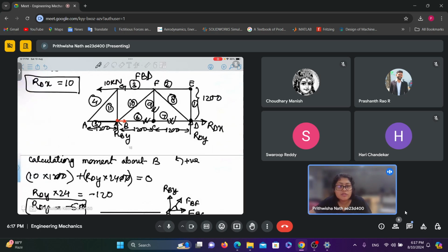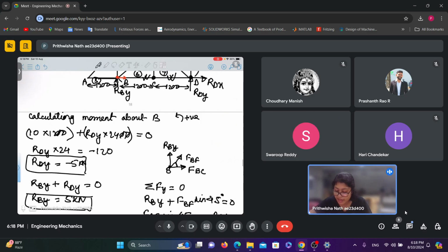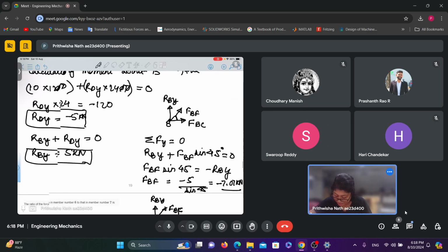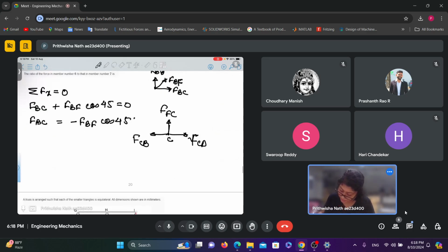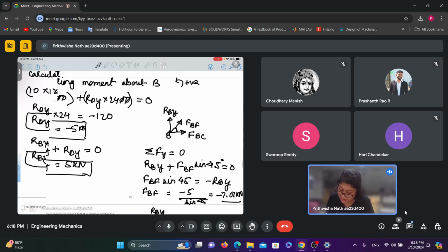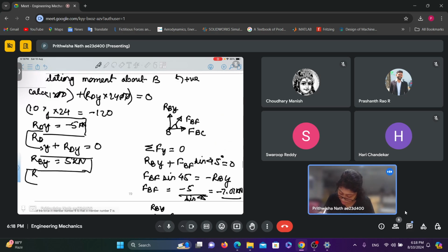We have already found out that member 9 is a zero force member, right? Yes, ma'am. Member 9 is a zero force member, so FBC equals FCD. FCB equals FCD. Now this member is member number 6 and this is member number 7.